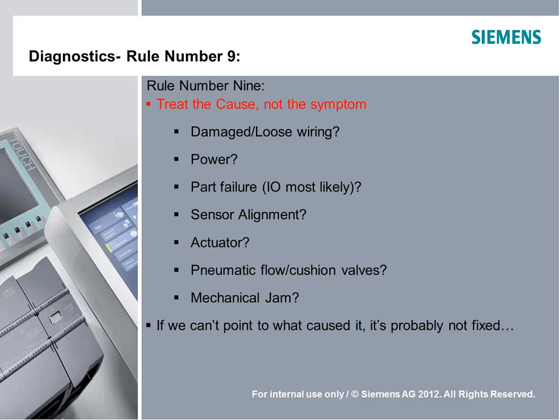Cushion valves and flow valves, which are used on the far end of the cylinder to slow its speed, tend to change over time. They may get clogged up, the air can get dirty, maybe a little bit of lubricant gets stuck in there. So just basic machine adjustment is sometimes all that's needed to get rid of what seems to be a very persnickety little intermittent problem. Mechanical jams.